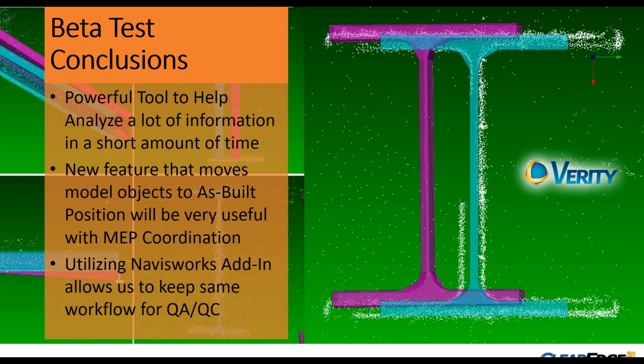So with the Trimble TX8, there are 3 options: a level 1, a level 2, and a level 3. Level 1 gets 500,000 points a second. Level 2 gets 1,000,000 points a second, and I'm not sure what level 3 goes. Level 1 rotates at 60 hertz and takes 1.5 minutes to do a rotation. Level 2 is about a 2.5 minute rotation, so you get an extra minute of scans. This particular one, I did a mix of level 1s and level 2s.